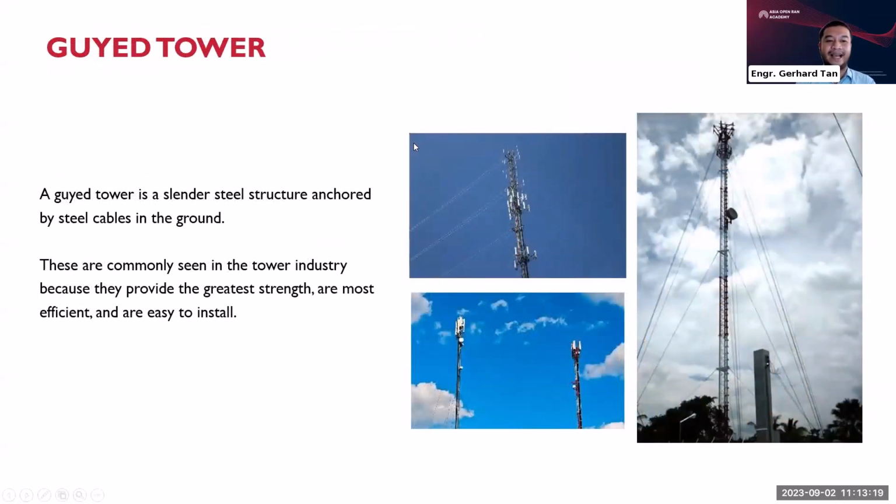Okay, so we also have the guyed tower, similar to an AM tower. There you can see the guy mast. This is to support the load of the microwave antenna, the base station antenna, and all other accessories. That brings additional load into the tower. So take note that this one needs a much larger footprint for the guy wires to be embedded into the soil. Once these are not properly designed, it will create a failure in the stability of the guyed tower.